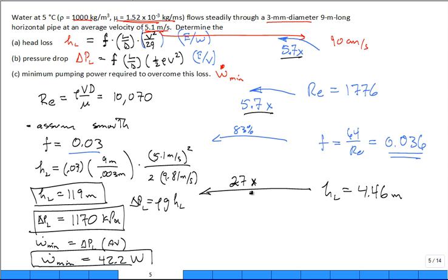The same with the pressure loss. And when you calculate the power, we calculated 0.28 watts, and it comes over here and it's 151 times. The power is a lot more because the power is a product of the pressure drop as well as a product of the volumetric flow rate. So V went up, and it affected the volumetric flow rate as well as the pressure drop.